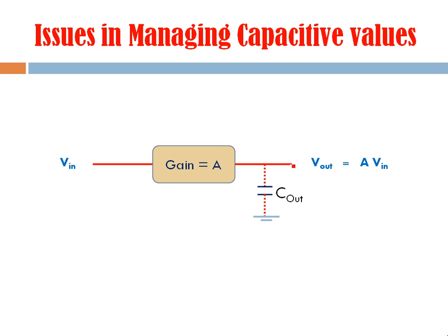The major capacitive component is connected between the output terminal and ground, indicated as Cout. Another major component is between input terminal and ground, indicated as Cin. Now there is a third major component connected between output terminal and input terminal, known as the feedback capacitive component.